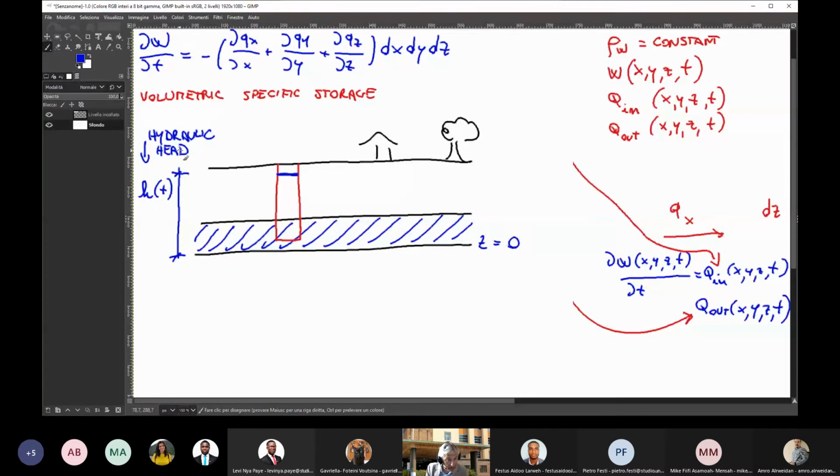If the water can come up along the well, it means that it has energy to climb up, and therefore it's a synonym of the energy, and it's also a synonym of the pressure of water in the aquifer. Of course, because the higher the head, the higher the pressure that this water makes on the aquifer. Okay.